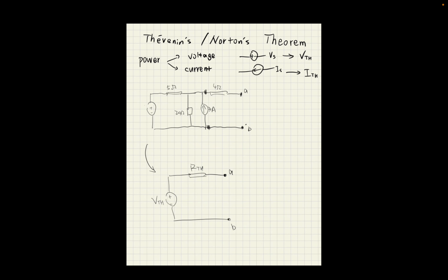And then, besides that, you should notice, this is important, because apart from providing 25 volts, when you're analyzing a circuit, an ideal voltage source also acts like a resistor with infinitely large resistance. So, to cancel that out, we turn the voltage source into a cable whose resistance is 0. That makes sense.